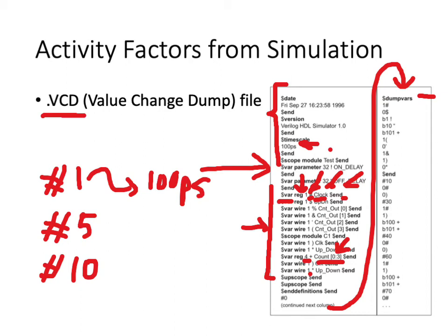That means if we have a long duration simulation and none of the nets in the design have any transitions, this whole dumpvars section will be empty. The way this is defined, it is a value followed by the symbol. So this section contains the initial values of the dump of all the variables.